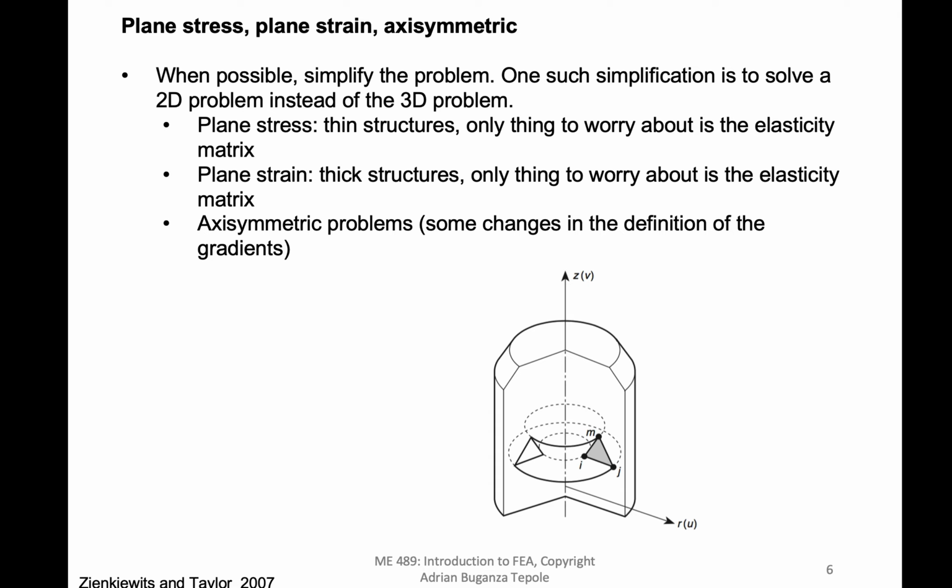And this is related to what we have been doing in the project. What you want to do initially is have a 2D approximation to the problem, to then find some characteristics of the solution and get a little bit more intuition about what the system is doing. It's not going to be perfect, especially if your part is actually 3D, but it's going to give you some idea of the stress distribution, and then you can upgrade to 3D once you have done a few simulations in the 2D case, the simplified case.